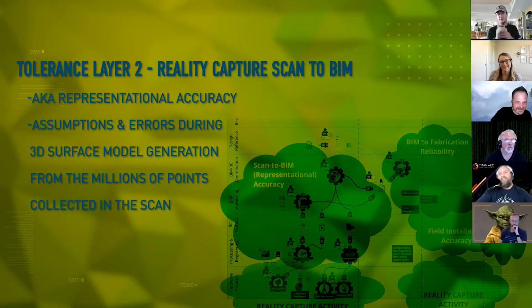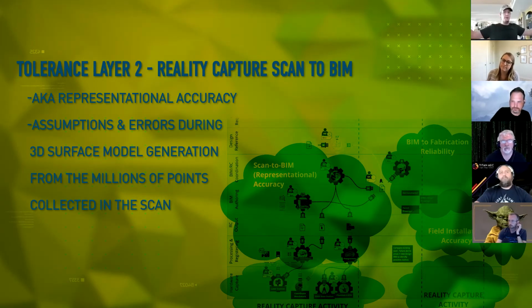I do want to make one point. It's better to do that cut down to 20 meters after you register, because those points far from the scanner, even though their range is less accurate, they are much better at controlling rotation. And rotation is actually your biggest driver of error in registrations. It's not actually translation, it's rotation. So you really want to use those longer range points for rotational control, and then cull them so that what you're handing somebody is only points within 20 meters or so of the scan. That way they get nice clean data. They don't see the long range data, but the long range data can still filter into the registration. So, just tossing that out there.